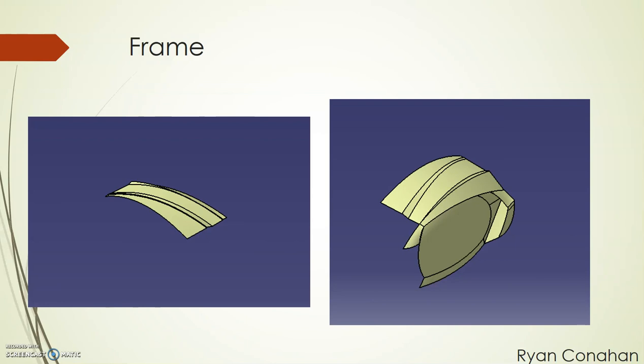So to start this part, we went through a lot of trial and error. Originally, we started with making it 3 parts. However, we discovered that GSD parts that need to be connected do not blend well together. So instead, to actually make this, we made it in 1 part file. However, we divided it up into 3 different sections.